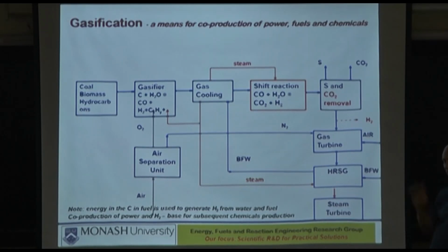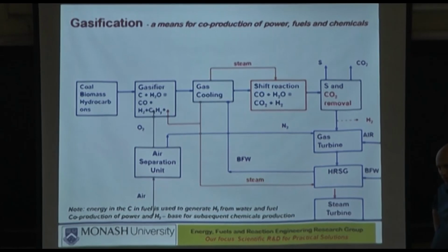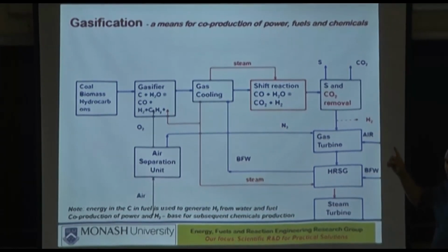So let us give an example. At 15 bar, the saturation temperature is about 220 or something. So say you put the water at 215 degrees at 15 bar. That water then has to become saturated steam, and then it has to reach all the way to the gasification temperature.